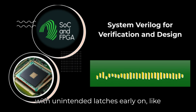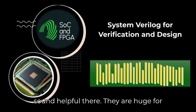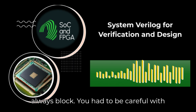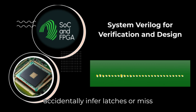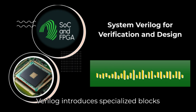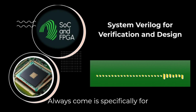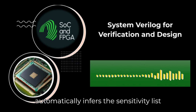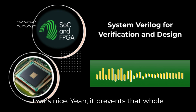I remember struggling with unintended latches early on, like chasing ghosts. These specialized blocks sound helpful there. They are huge for that. Verilog just had the general always block. You had to be careful with your sensitivity list, or you could accidentally infer latches or miss updates. Right, forgetting a signal in the list. Yep, classic bug. SystemVerilog introduces specialized blocks that make your intent crystal clear. always_comb is specifically for combinational logic. The beauty is it automatically infers the sensitivity list from the logic inside the block. Oh, that's nice. Yeah, it prevents that whole class of bugs.